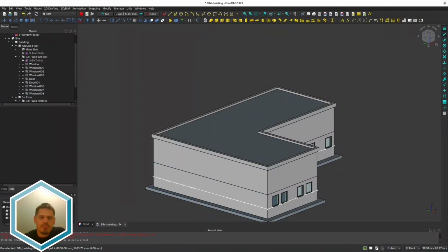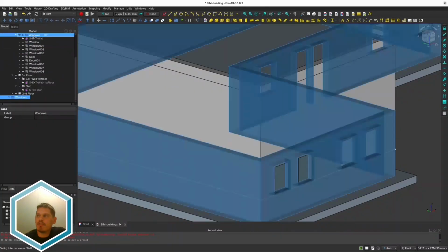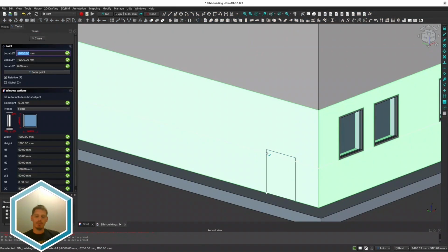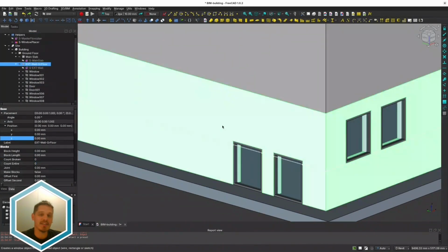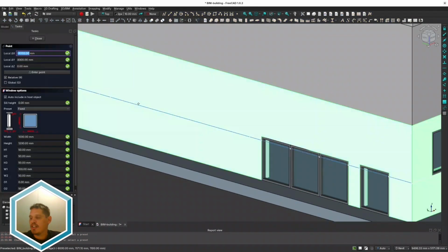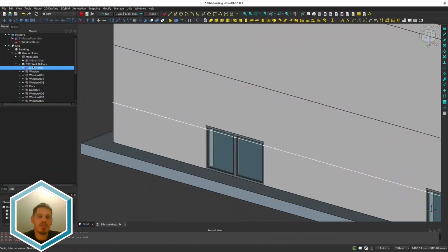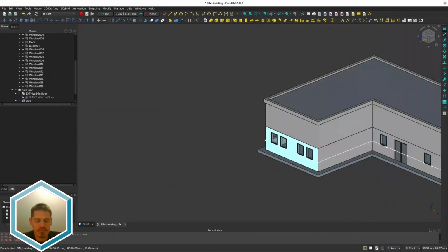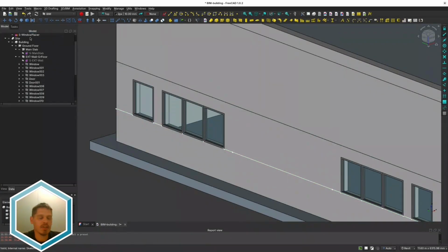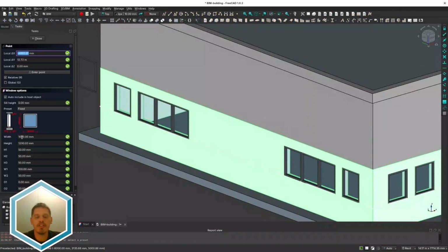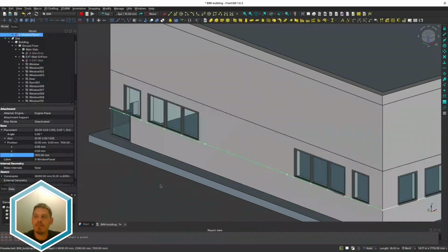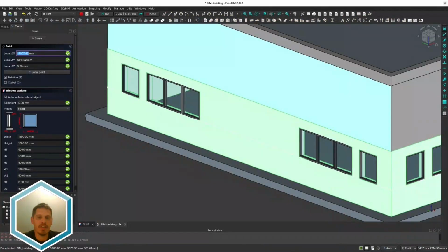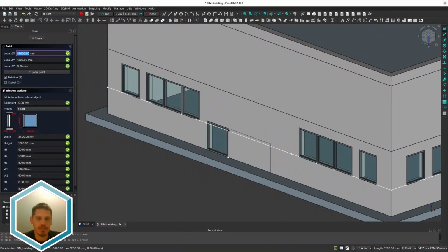So back to how you would make BIM actually work. Well, not if everyone uses different programs, and the solution is definitely not that you go to a different engineering company and we want you to do an engineering package for us, but you have to use this software, and everyone has to retrain. Not that that's so difficult nowadays, but what you need are formats that every software can use natively, and that's where IFC comes in.